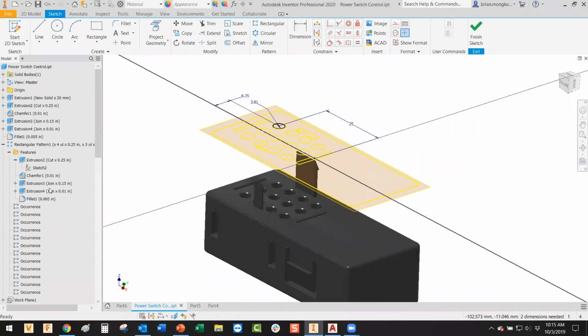So if you want to use an existing sketch, but you want to create your own new sketch, you can use that method there. Yep, and there's just multiple ways of doing things too. Like with the copy sketch, it doesn't have a link to the original anymore, right? So if that original hole changes or the original sketch down there changes, this won't update. But if you project the geometry, it's associative.